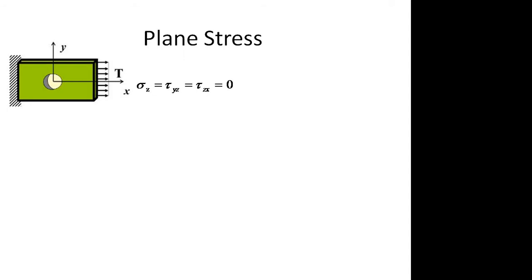The stress component developed along the z direction will be very, very negligible. So these kinds of problems, where the length and width are large and we are not preventing the other side from moving, we can say it is a plane stress problem. These we solve as plane stress problems.